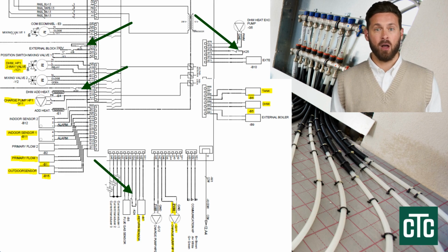In the next video, I will show you how to perform the initial system startup and configuration. Please do not forget to install a magnetic filter on the return pipe to the heat pump. It is intended to protect both the circulation pump and the heat pump from dirt and debris.